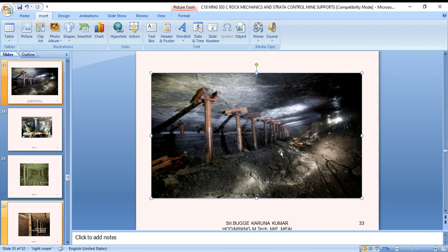Dry and seasoned sal props and bars are used in some parts of the area also. Presently, steel props are used due to timber's erection problems. Most of the hydraulic props are set when erected in a mine to support the roof, and should yield slightly under the roof weight. The timber prop is strong when the load acts parallel to its length. A prop as such is almost unyielding, but a certain yield is obtained by tapering it at the foot or top, providing a lid on the top of the prop as a compressible cushion between the roof and end of the prop.